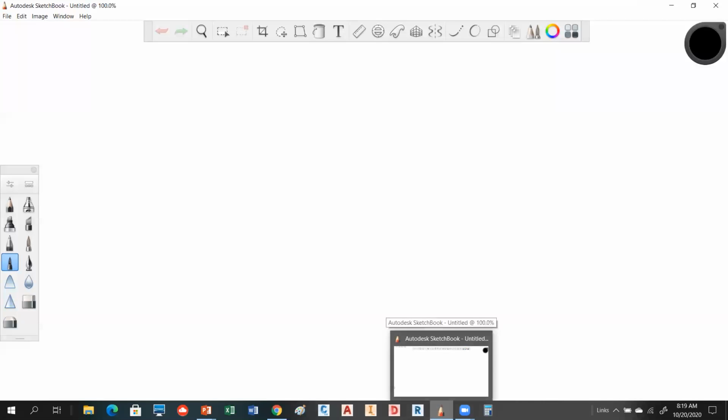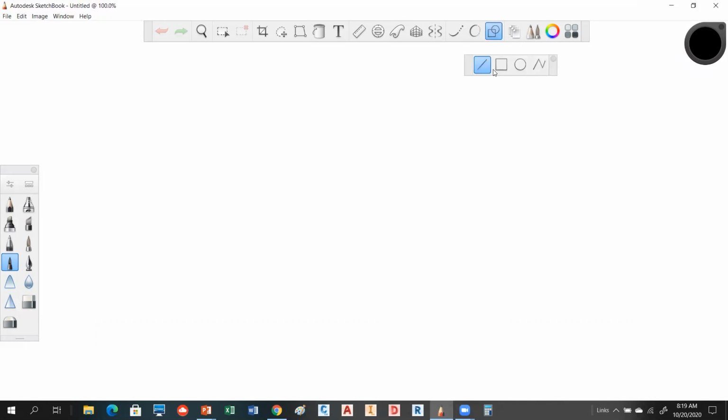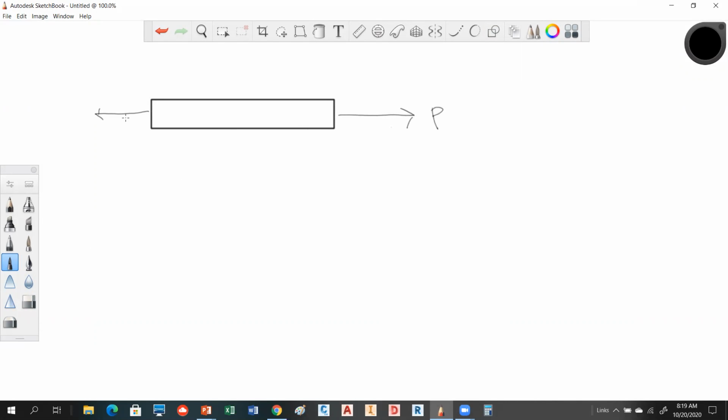Okay, so in this case, let's look at what we've got here. There's a part that we're dealing with, and we're putting an applied load on this. So if I'm applying a load this direction, and in this direction, so this is a force, and this is a force. Notice the force is axial with this, okay? And you could see that we are putting this in tension, so we would be dealing with a tension stress. So if I cut a cross section here and look at that area, let's say this is a rod, then what I'm getting is a cross section that would look like this.